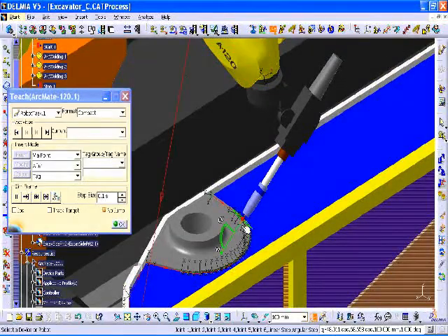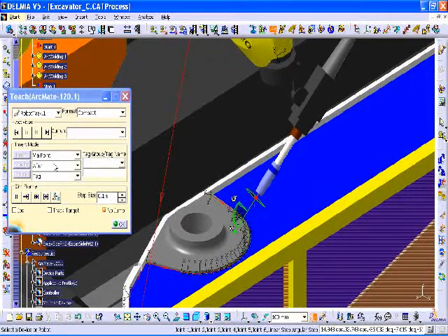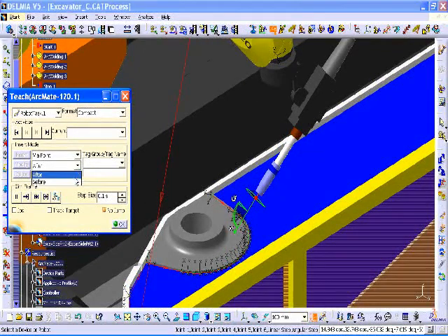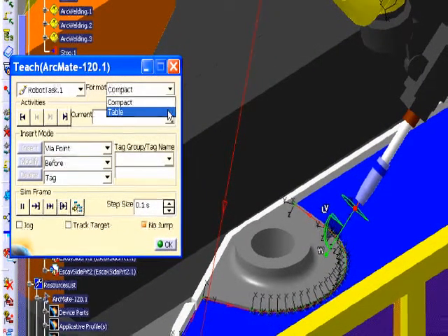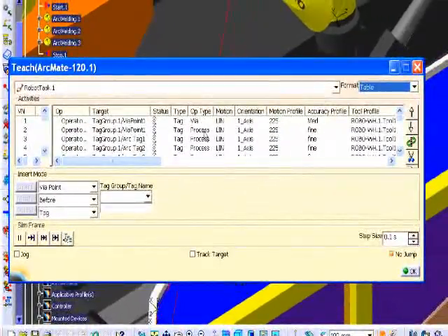Now let's look at what we call the Robot Teach page. This lets the engineer add and delete robot locations, as well as modify the motion parameters of the robot path. You can insert via locations before or after each weld path for ingress and egress to the welds. This also is where we can dress the path with specific information for the robot to follow.